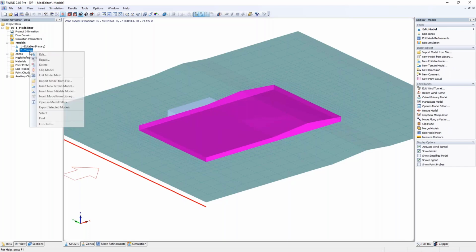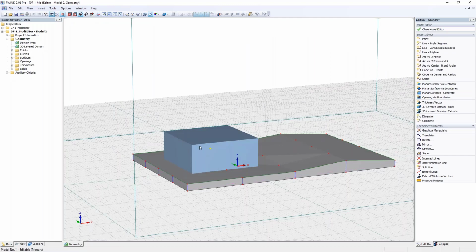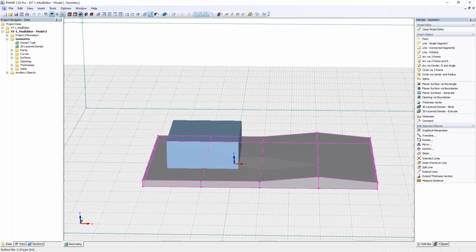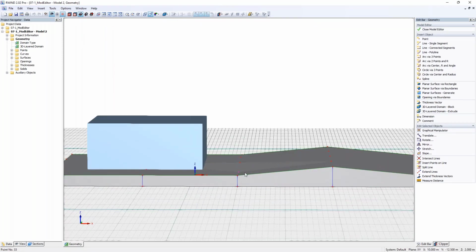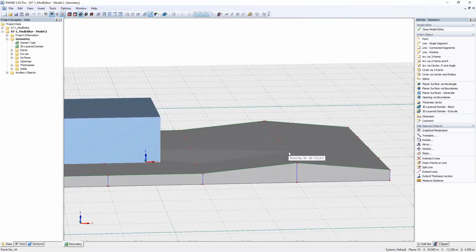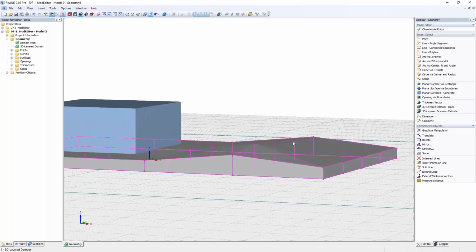And as already told, you are also able to insert the terrain. So we can also open this in the model editor, and then you can see your construction and that you have some thickness vectors over here. And that's quite easy then. You can, of course, also define the amount or later on copy some more thickness vectors into the terrain to simply modify the nodes. So if you double click it and you think that the thickness of the terrain is 6 meters in there, you just adjust it.